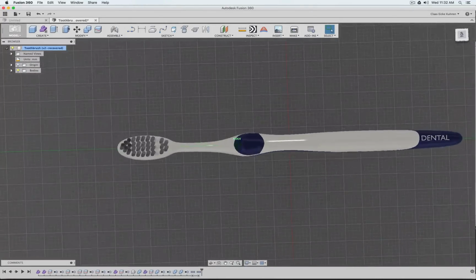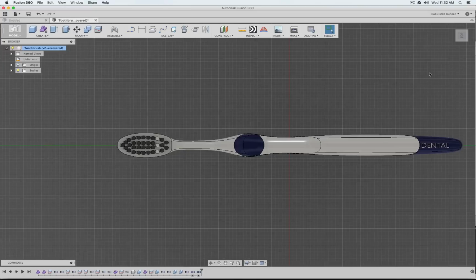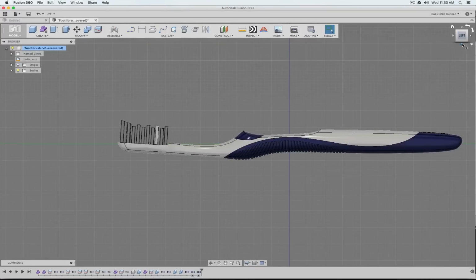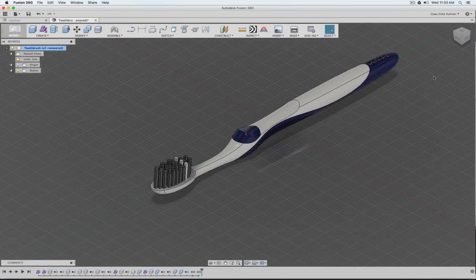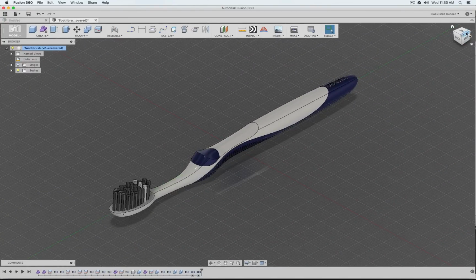With the way Blender gives us modifiers and subdivision surface and booleans, we can, as you can see here, create a design very fast in Blender, and then when we bring it over into Fusion, we don't have to rebuild everything. We just convert the geometry type, and then we just recreate the boolean, trimming and cutting and joining, and that's it. So all the work we created in Blender is not lost.